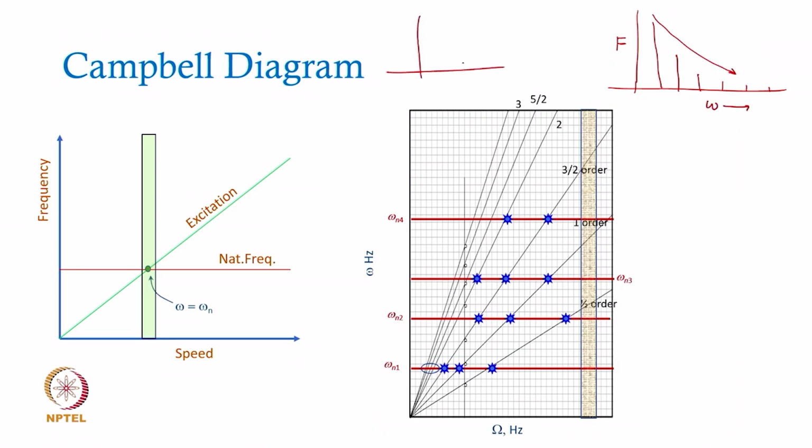If I have an excitation function like this, quite similar to that gas torque that I have shown you, and I decompose this and then plot the Fourier coefficients, all the components of the Fourier series, I told you that their amplitudes quickly decay. I mean, the higher harmonics will have less amplitude, right.